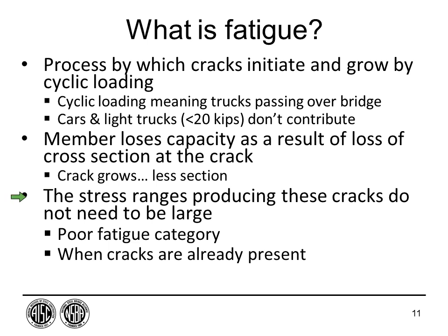Another important point, and we'll see some of these numbers, is that the stress ranges, the cyclic stresses, don't have to be all that large to cause damage. That's particularly true where you have a category, and we'll talk about what I mean by that, a classification of a fatigue detail that isn't very good in fatigue. We'll see some are better than others. Or if I already have a crack present. And then, of course, when I have a crack present, cracking can just continue at very low stress ranges.